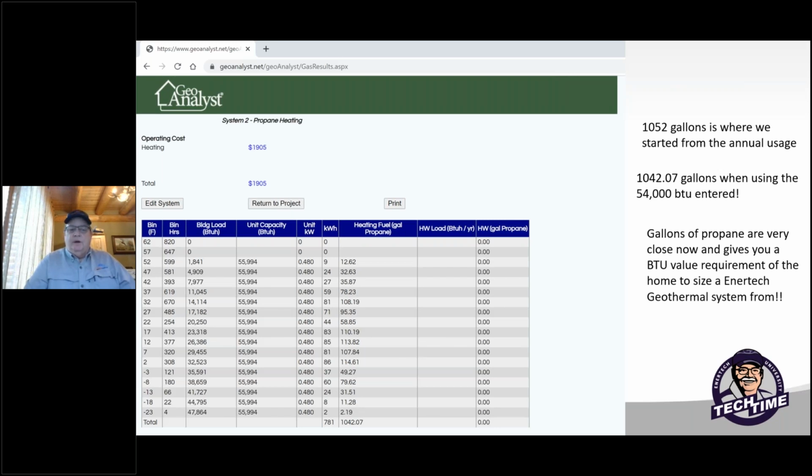And again, from my previous presentation, ductwork is very important. The layout of everything is important to look at the whole aspect, but this is a fast, closer way of determining a BTU requirement for a home. You can also use this as a means to double check if you're going to do a Manual J load calculation. You can do both of them, compare and make sure that you're accurate. So this is another shortcut way that I wanted to show you of how to look at the total home BTU requirement.